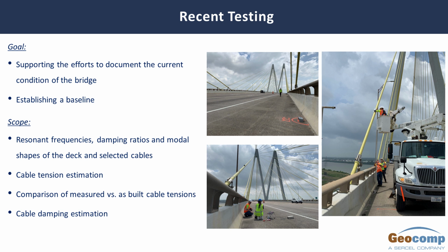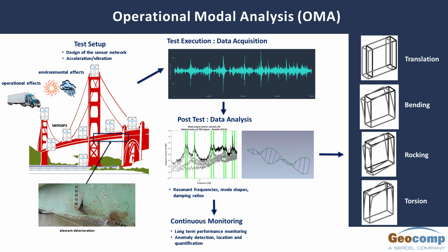So just to clarify, for this bridge, we didn't have a chance to test everything. We only looked at selected cables, and we didn't have a chance to disconnect the dampers and do a before and after damper study. So we just tested them as the dampers were already connected, and our results will indicate that.